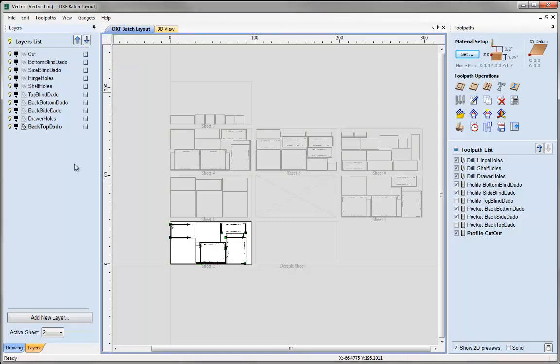You would then navigate to that toolpath template, and the gadget will automatically apply the toolpath template to every single sheet for you, with the option also to create the post-processor code directly without having to go ahead and save all the individual toolpaths. But it does create the toolpaths for you, and that will be indicated by S1 underscore and then the particular toolpath name, and then S2 for sheet 2 and then S3 for sheet 3.